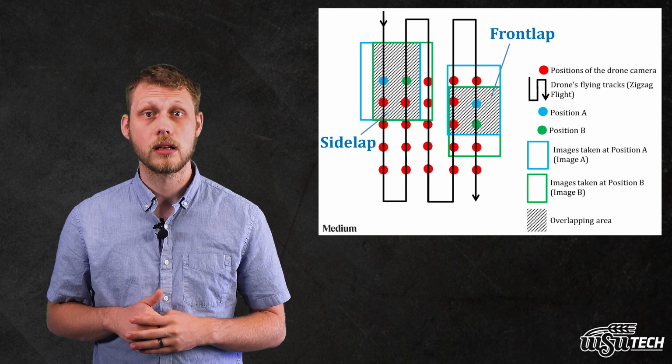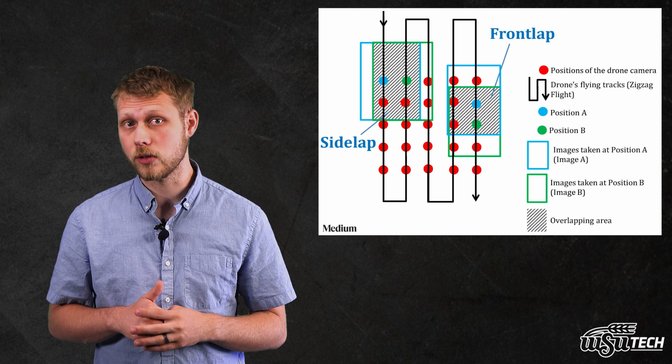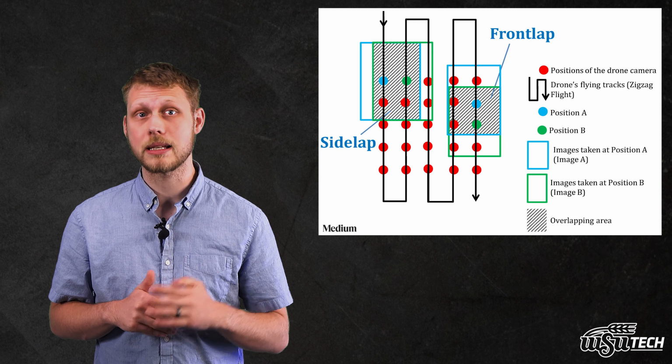Photogrammetry involves capturing overlapping 2D images, then stitching them together into 3D models, maps, and orthomosaics. The better your images, the better your model. When it comes to inspections, a bad model doesn't just look bad, it can miss critical damage. Start with a solid flight plan. Use around 75% front overlap and 70% side overlap as a baseline.